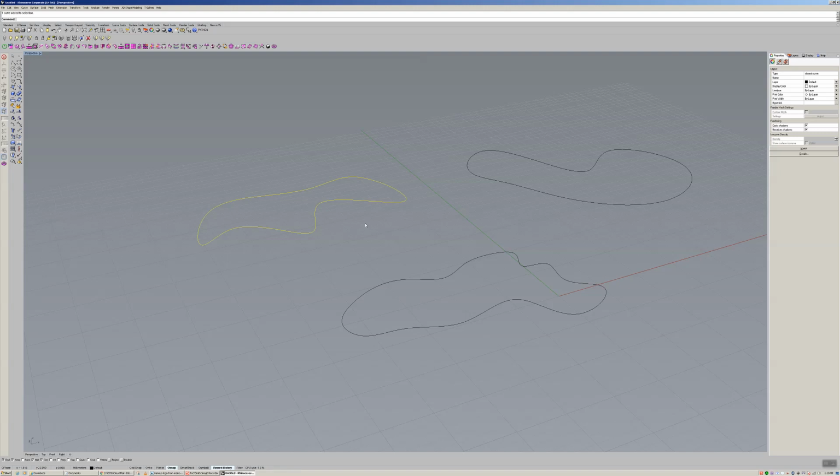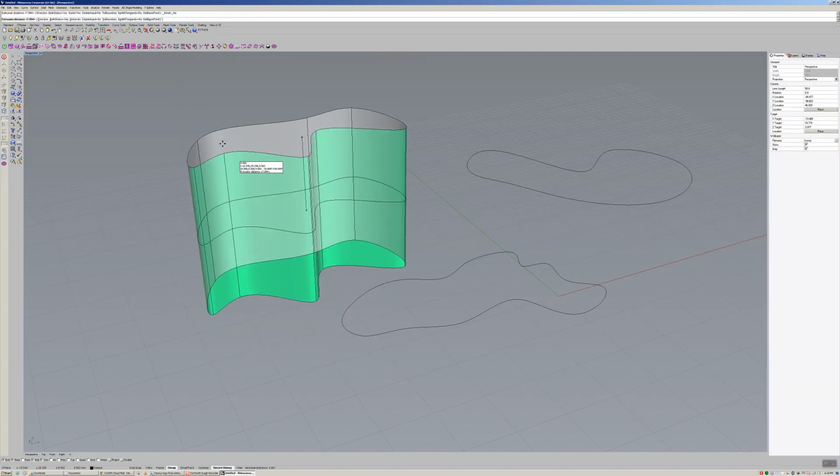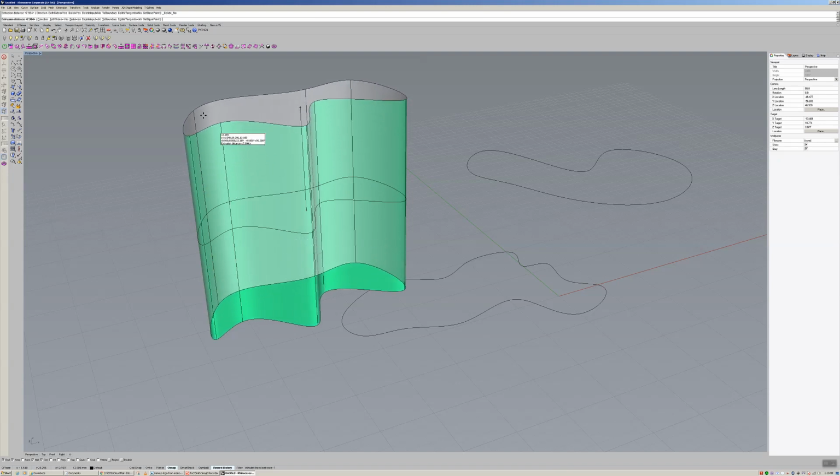All right, I'm selecting the curve. Now this is a new command you're going to learn here. The shortcut is Control-E, but we have to set those up. That's my shortcut, Control-E. The long way is I'm going to go under the menu, and over here it says Surface. I click on Surface. I come down to Extrude Curve. Now I have several options. We're going to go straight. Extrude Curve Straight. Left click on that, and as you can see, it's making that curve into a surface and extruding it 2 directions. We don't want 2 directions.